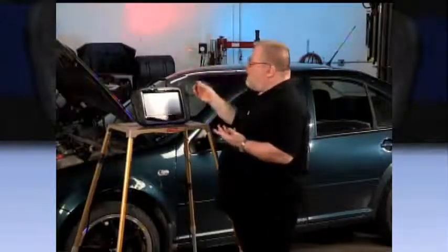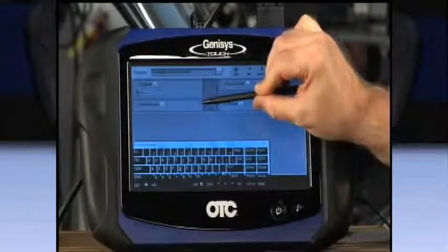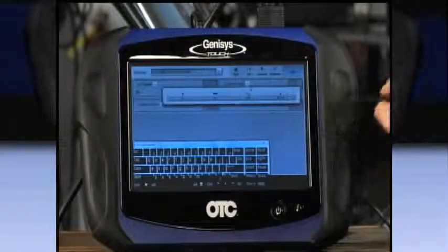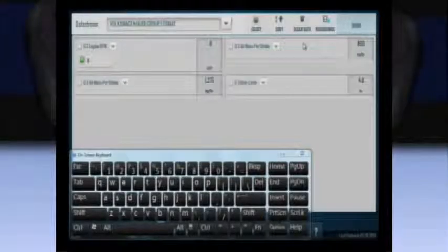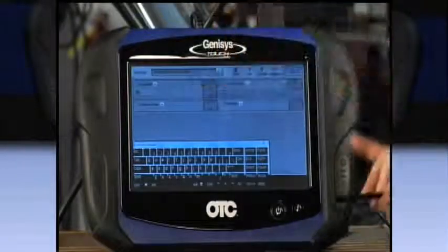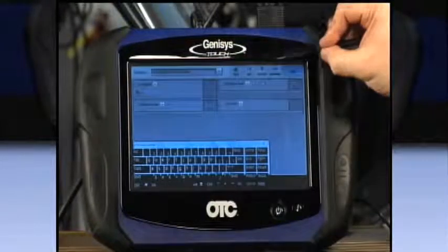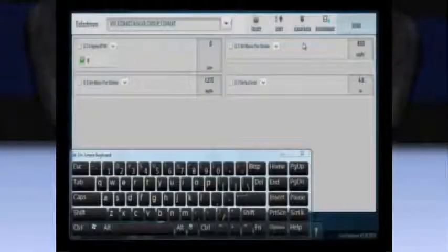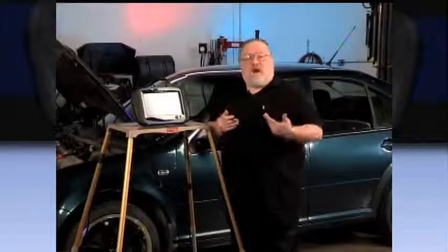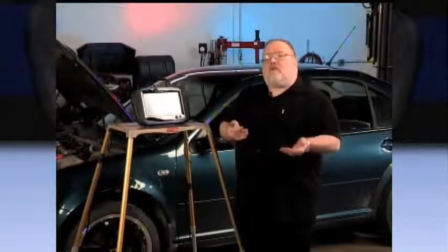What we're interested in, though, in this particular case, is that the data measuring block shows 4 fields, 1, 2, 3, and 4. Each one of these fields is a specific bit of data that we're interested in. For instance, field 1 is engine RPM, field 2 is the mass airflow sensor reading, field 3 is the air mass reading again, and field 4 is the actual duty cycle of the EGR valve. Now, why is this important for diagnosing a low power condition? Well, one of the things that can cause low power in a diesel is lack of airflow into the engine.